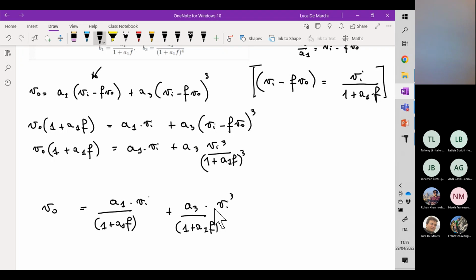So we add this PD, this dominant pole, and by this addition, the A of j omega curve is modified, in the sense that we have now the behavior highlighted by the dashed curve, in the sense that after the dominant pole we start losing 6 dB per octave, or if you want 20 dB per decade.